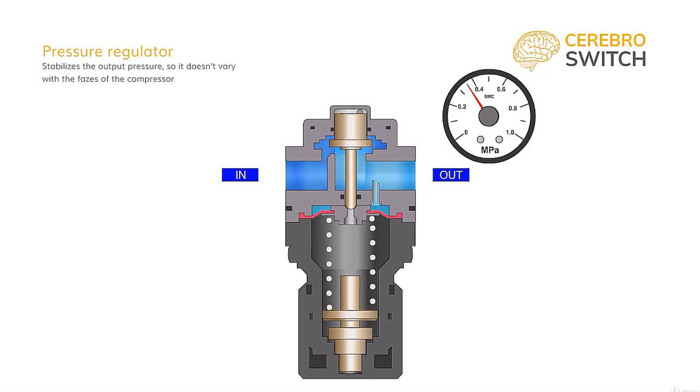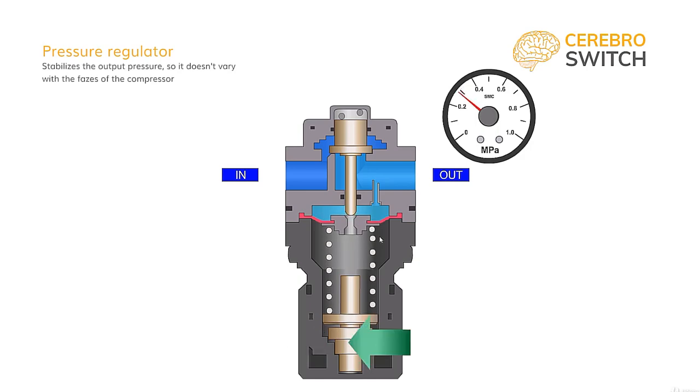The last thing to know about the pressure regulator is that when you lower the pressure, or we even go as far as shutting it, on the imaginary right tank, there will be a higher pressure than the setting. This, in turn, will push the rigid disc further against the spring, and the entire pressure present in tubes, valves, and cylinders will be exhausted through the center of the disc to the atmosphere.